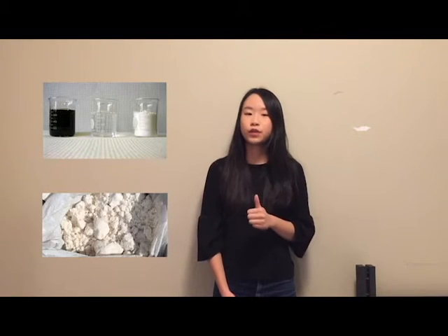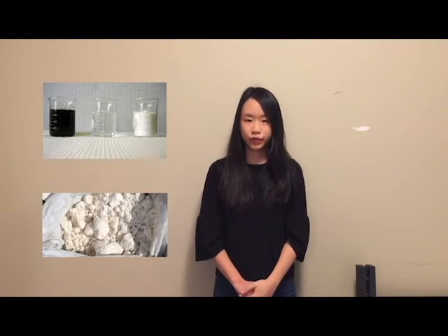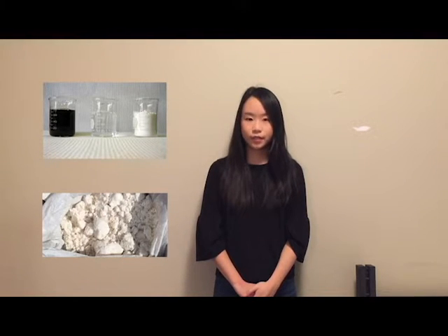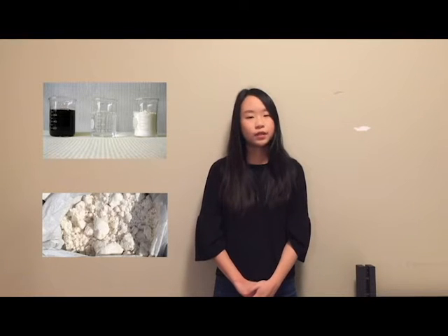How this works is the salt maker is essentially a mobile facility that features low temperature evaporation combined with crystallization that reduces wastewater down to two outputs: fresh water and solids made of reduced contaminants. This technology achieves true zero liquid discharge while operating at a relatively low temperature from 60 to 90 degrees, which theoretically eliminates the cost of trucking wastewater down to a designated disposal area.